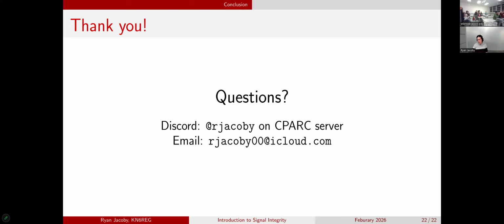Whatever application you're doing has some kind of application note, which will tell you approximately how much signal skew you can tolerate, and you can take that, put that into KiCad, and it will tell you whether or not you're meeting the constraints you give it. It's actually very, very nice. I've done this on a couple of my boards.